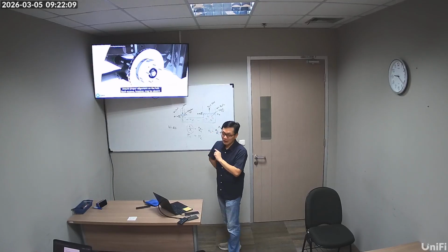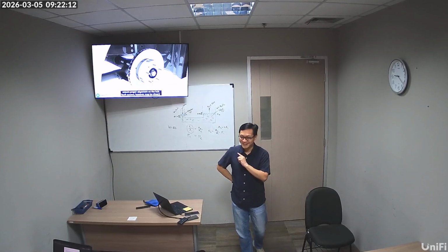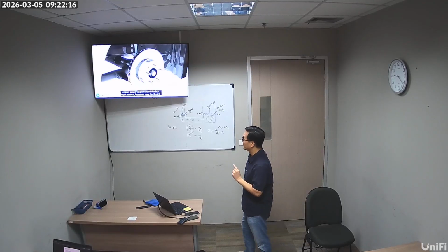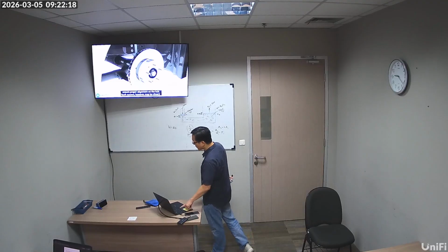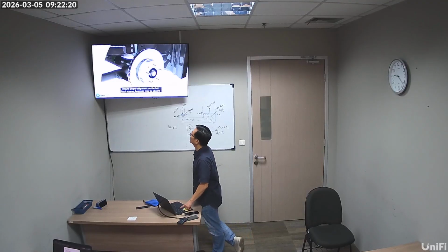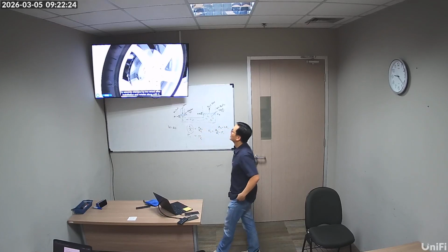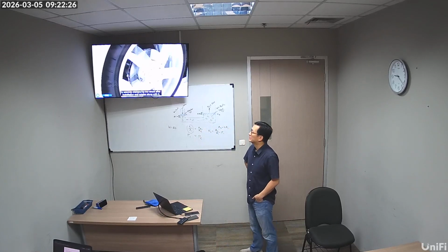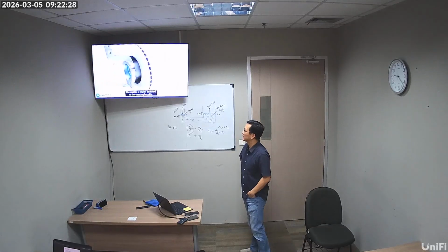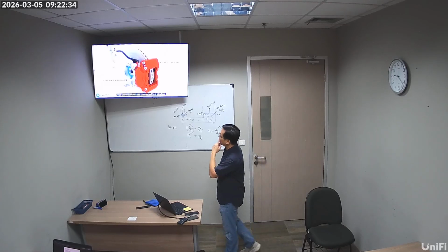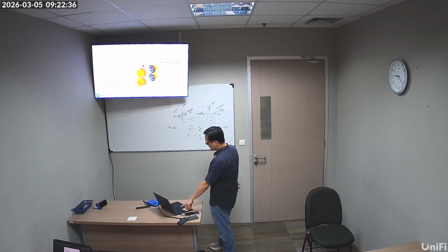But those two screws look small, don't they? But they're not the ones holding the brake rotor, by the way. What is holding the brake rotor? The wheel itself. Next, the brake disc is securely clamped by the wheel after installation and rotates along with it. The caliper is rigidly attached to the steering knuckle. The slave cylinders are connected to a flexible hose that delivers brake fluid.